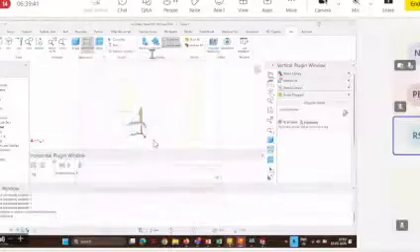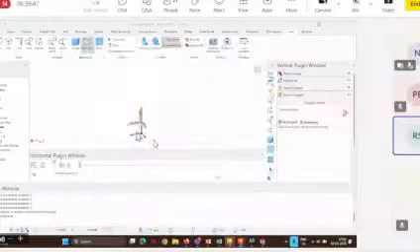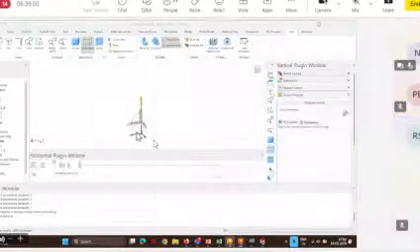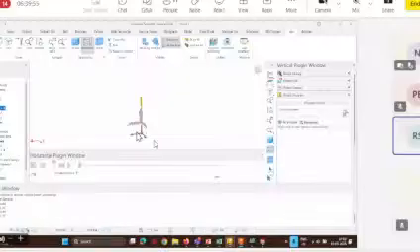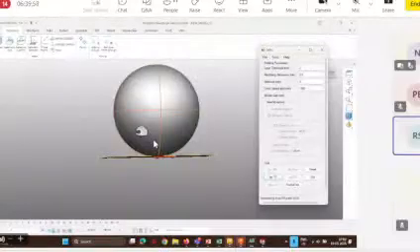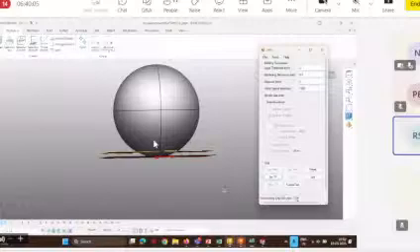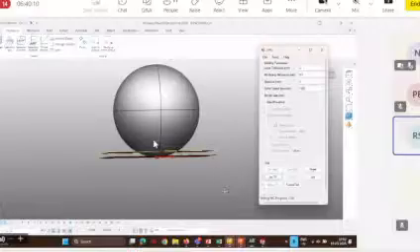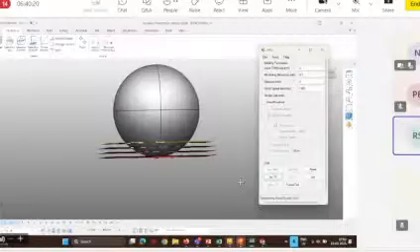Now you can see it's popping up between these two windows. Basically, it's transferring the layers one by one, creating the toolpath and tools, and generating a toolpath over here. You don't need to do anything. All of it is done by this macro. The only thing we need to do is put it in the loop. Now you can see it's generating the NC file. Transferring data, one is completed, then two is going on. Like that, the entire model will be completed. Sometimes it takes some time depending upon how big your model is and how complex the steps are.